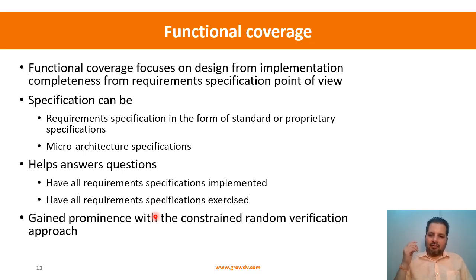So whatever is extremely critical for you, not only do you design it, but you also define the functional coverage plan around it and implement it in a very detailed fashion, so that it has really been exercised. That is why functional coverage has become important with randoms, since there is no 100% guarantee that it is going to really hit certain scenarios. If a scenario is important, you define the functional cover point as well and make sure that it has been exercised.